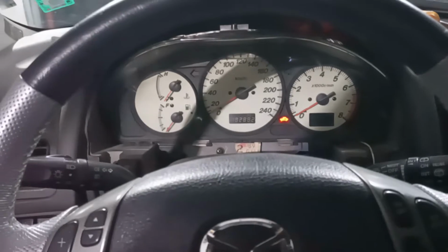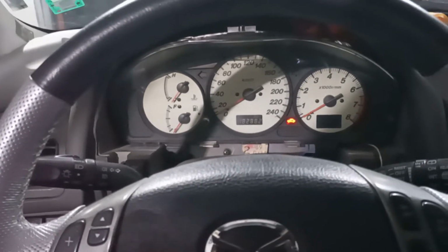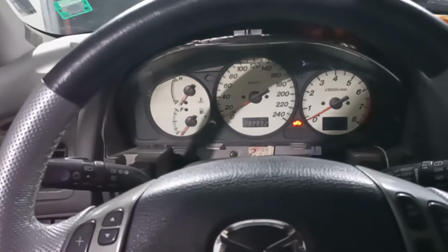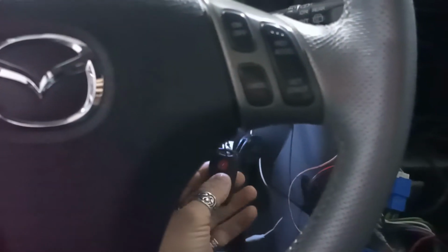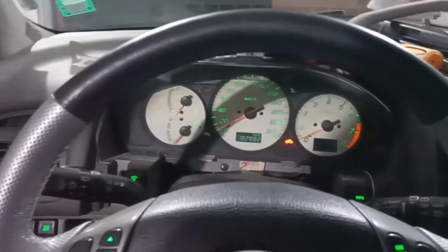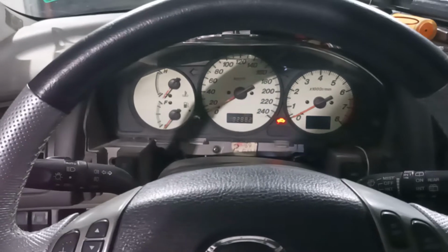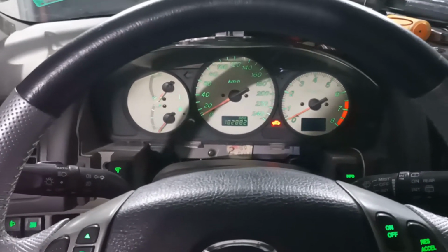We do not care about parameter 1, although this will be the most important one when you're actually installing the module. We want to go into parameter 7. For that, you unlock the car, either you click this, or lock and unlock the door. Now it blinks and beeps 7 long times, because this is parameter 7. Then the value.